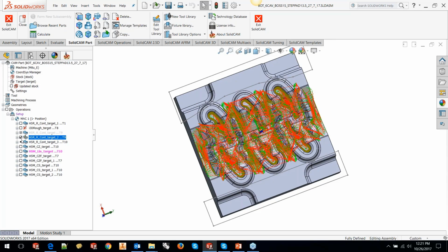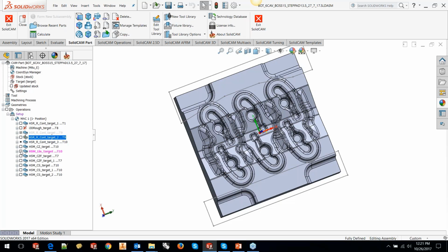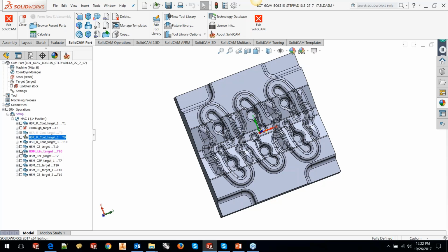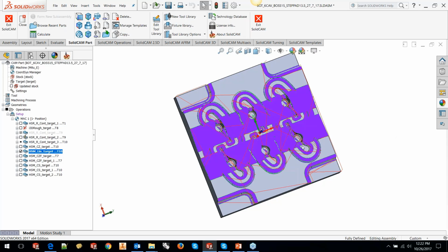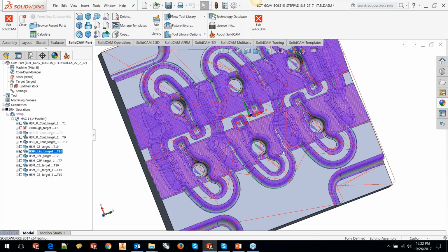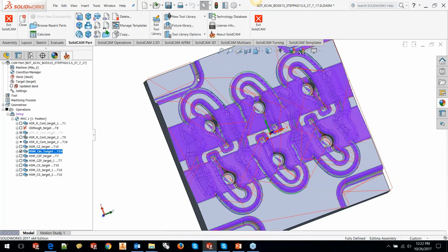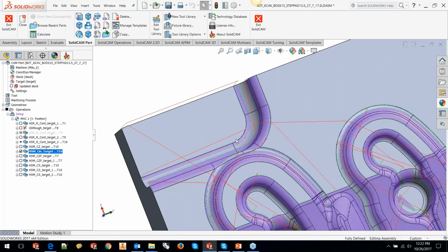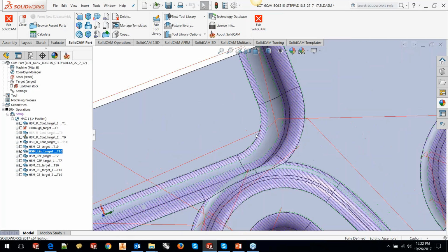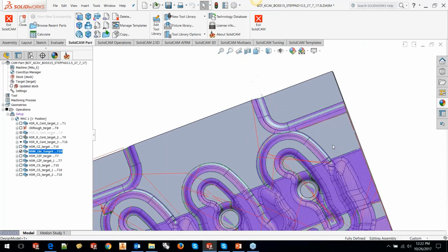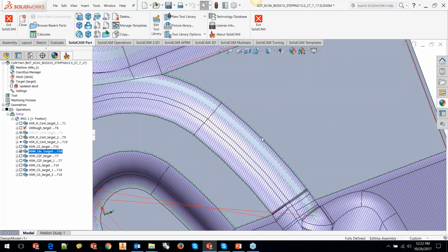Okay, so one of this is that, and the next one is a slightly more complex toolpath editing, because this is generally what is seen in finishing. The slope angle itself has a limitation. It's a process kind of a limitation, and you can see that it's machining this fillet, it's machining small portion of the fillet here. Okay, it's doing a lot of unnecessary things that I don't want it to do. For example, it's also doing this one halfway here. That's because of the slope angle.